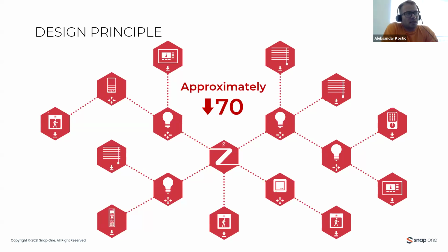Of course, as a Control4 controller is acting as a Zigbee access point, for good and reliable Zigbee communication it is really important that we have good visibility between the Control4 controller and the Zigbee nodes, like lighting controllers.